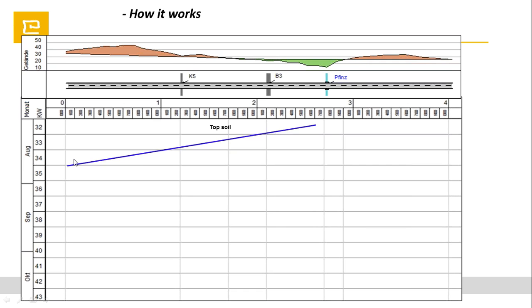If your project manager or your investor requires from you clear and advanced control at each 100 meters, and you don't have this diagram, what do you need to do? Let's say that you are using Primavera or Microsoft Project or Asta Powerproject, you need to create an activity called topsoiling, starting from 2600 to 2500. And another activity 2500 to 2400, and another activity 2400 to 2300.